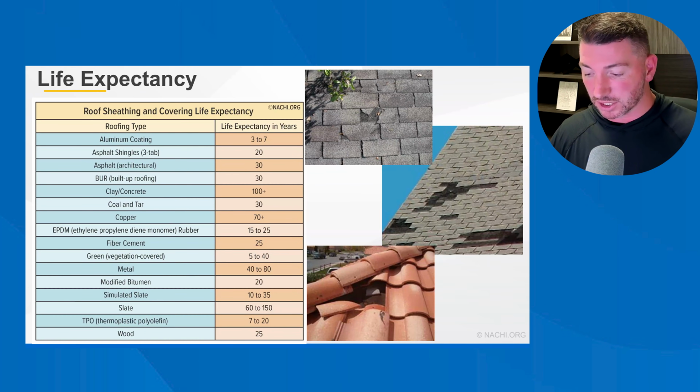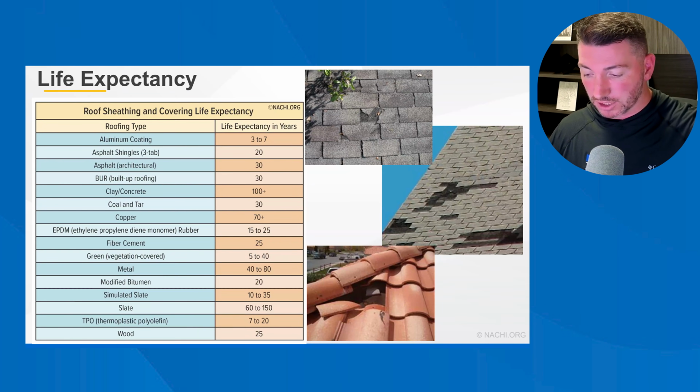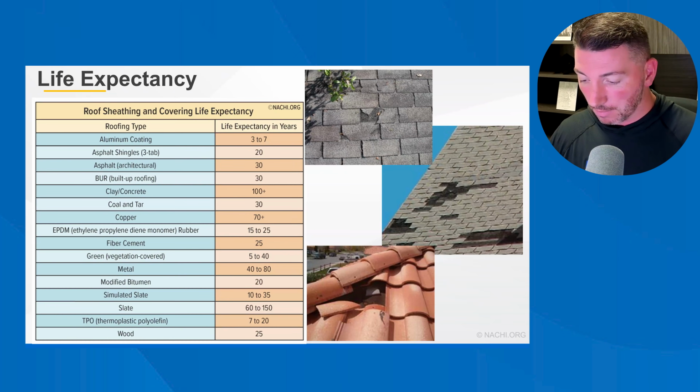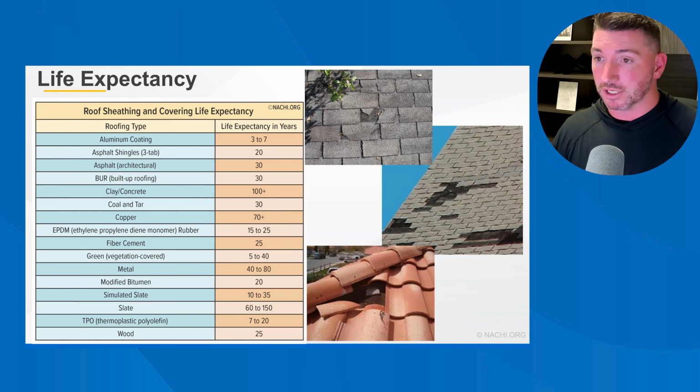A south-facing slope tends to show signs of overheating, particularly with asphalt shingles. And then north-facing roofs and those in the shade tend to have more algae and moss-induced problems, both of which could shorten the life of the roof covering. The sun is definitely more damaging than a lot of those organic growths. In fact, algae causes no damage to an asphalt shingle. It builds up on the surface, and it actually serves the purpose of holding the granules on, which are the primary